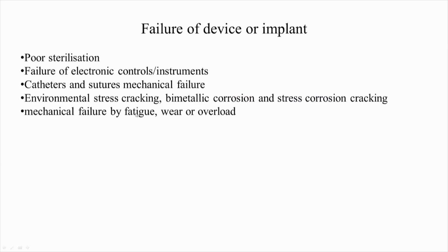So wear, fatigue, like I said, diaphragm valves, joints, knee joints, they may undergo fatigue, wear, and the ball and socket, overload. So you are putting too much load, so the materials could break or crumble or crack because of overload. Stress shielding. So we have stainless steel or titanium implants going parallel to the bone, so most of the load is taken by these metals, so the bone loses its load carrying capacity, so stress shielding can happen.